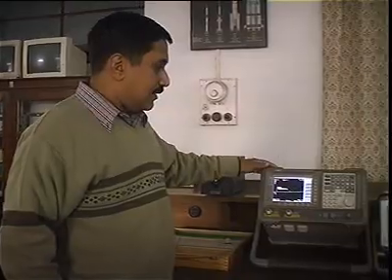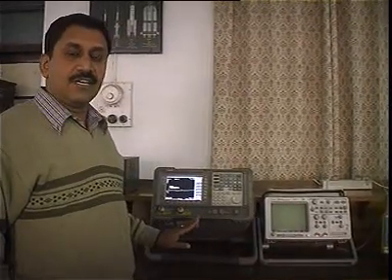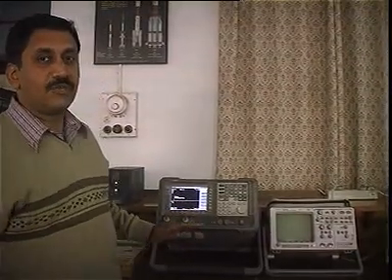Now, you have a similar thing for the oscilloscope also. All these things are listed here in the front panel of the instrument. There's another important thing to do with this, which is that you should worry about how much maximum power you can put in. Now there is obviously a limit. This instrument can take a maximum of 1 watt, plus 30 dBm. If I put in power more than 1 watt, this instrument is likely to get damaged. Okay, so it is important that we pay attention to all these factors before we begin to use the instrument.